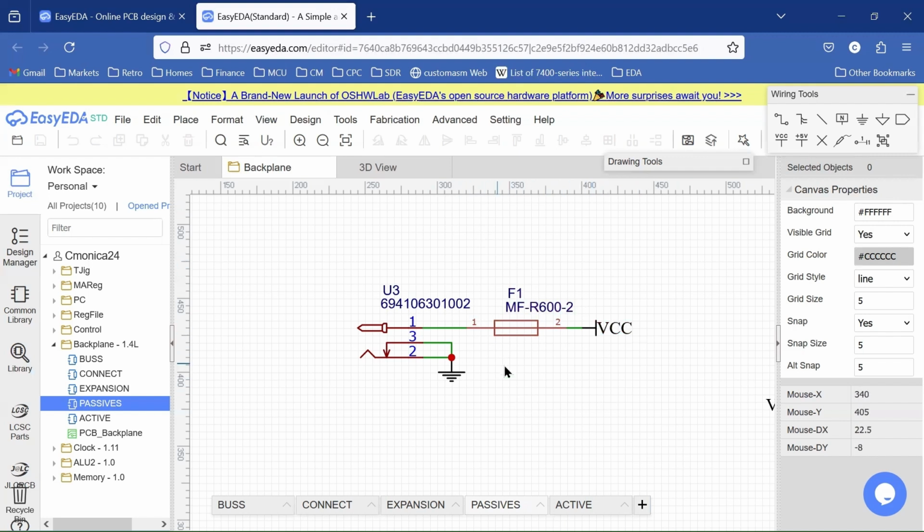So what I think I'm going to do is I'm not going to use the resettable fuse. Our circuit board's already designed, is already manufactured. What I'm going to do is use the inrush resistor thermistor here instead of the resettable fuse, because that's really the more important thing. The resettable fuse is really just an outlier condition, right? We don't want that to happen. We don't want to ever reach 6 amps, and we don't ever want to have a short circuit.